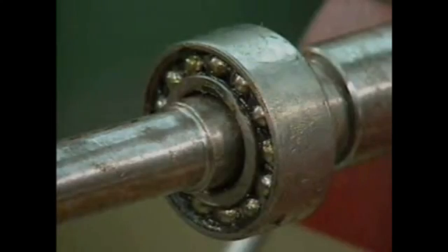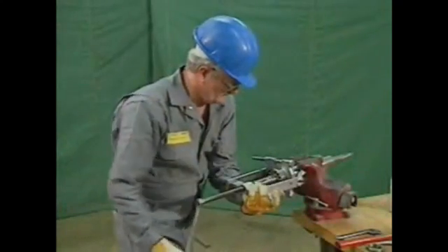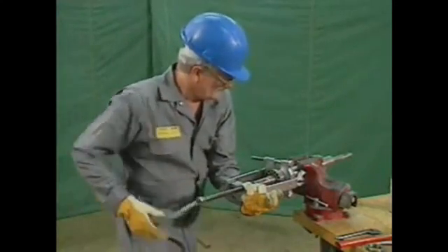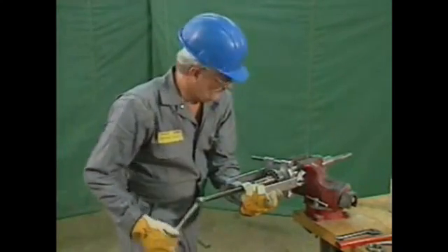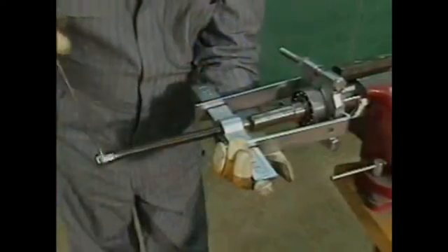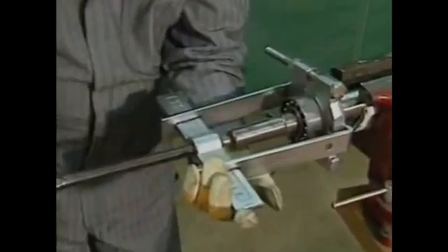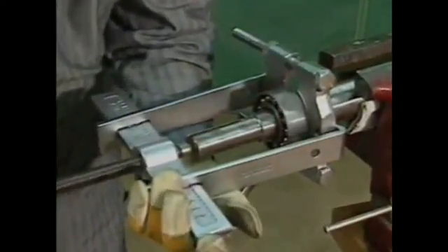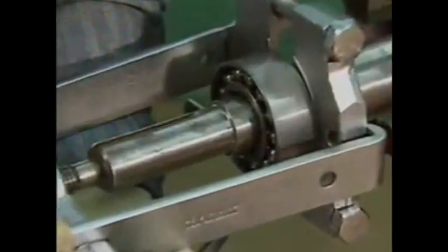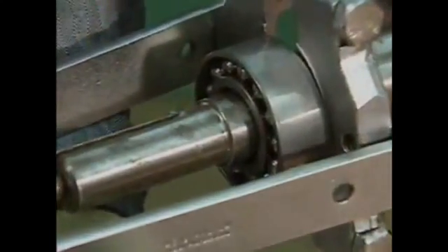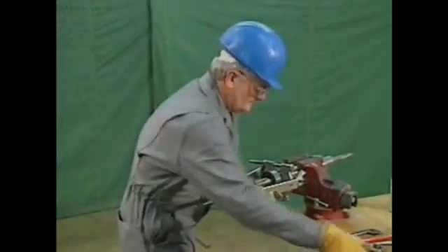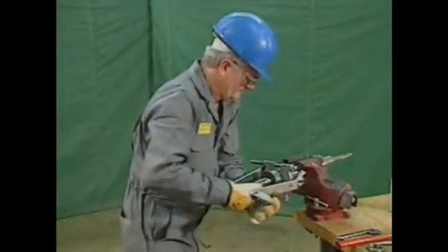Bearings that fail must be replaced. In this part, we'll watch a mechanic prepare to install a new rolling contact bearing. The mechanic begins by carefully removing and cleaning the damaged bearing. After a bearing has been removed from a shaft, it should be handled carefully. It should not be left where it will get dirtier, and it should not be rotated, banged around, or dropped. Handling the bearing carelessly will only make the task of determining why it failed more difficult.